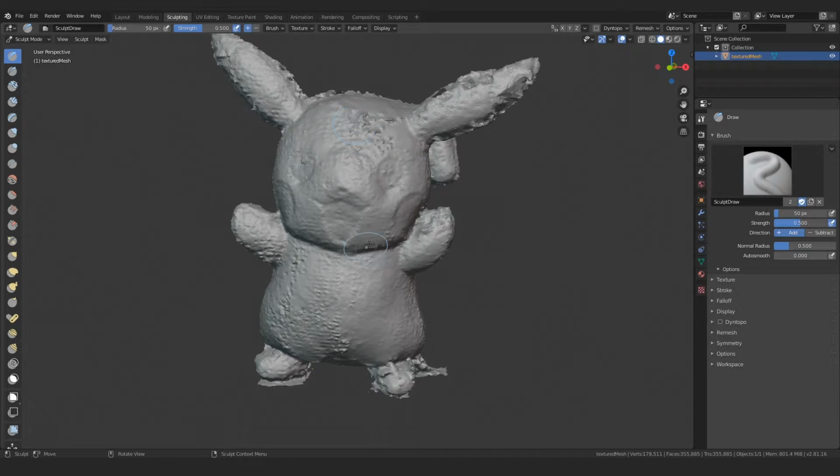Now the goal of what we're doing here, like I said, is to smooth the model out. We're going to look at any jagged peaks or any nasty parts of this model and smooth them down, with the specific idea that we want a smooth contiguous surface. Because when we reproject the texture from this original model onto the new remesh model, if we have any jagged pieces penetrating through the new model, it's going to give us problems.